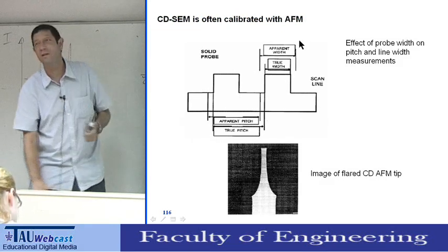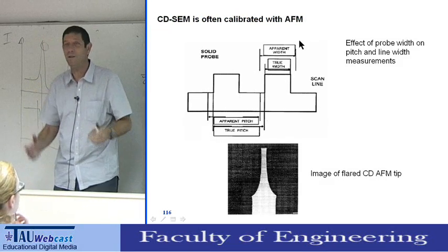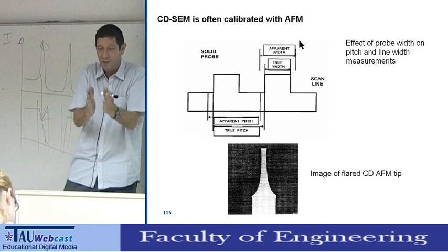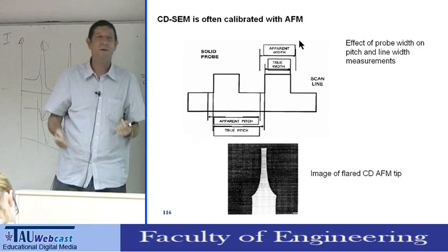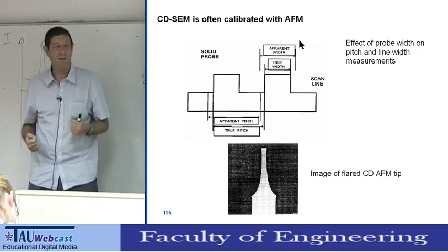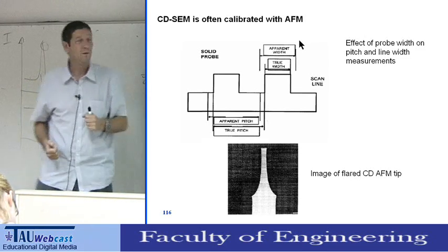So how do you calibrate? One of the problems is how to calibrate the SEM. You measure a certain image on the SEM, but the image depends on the sidewalls. So one very common option is to calibrate with AFM.